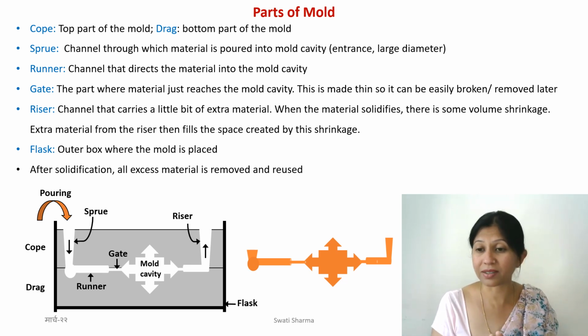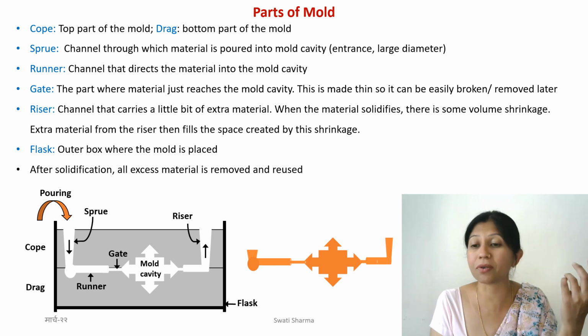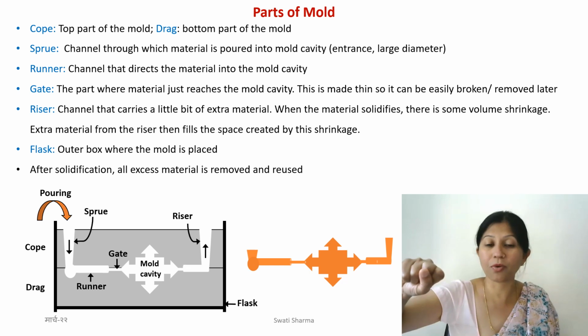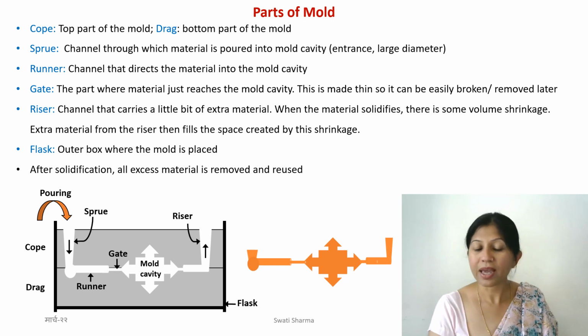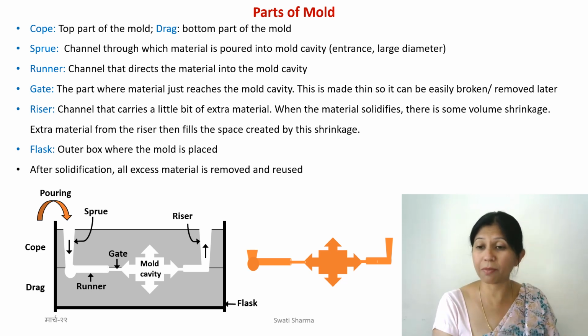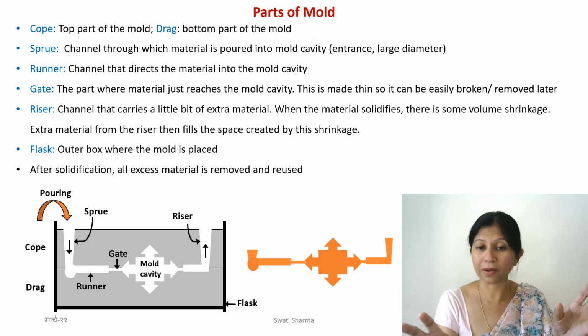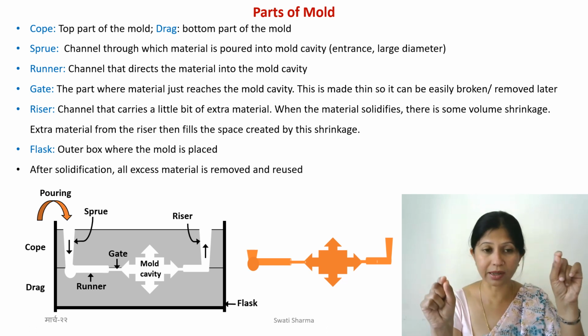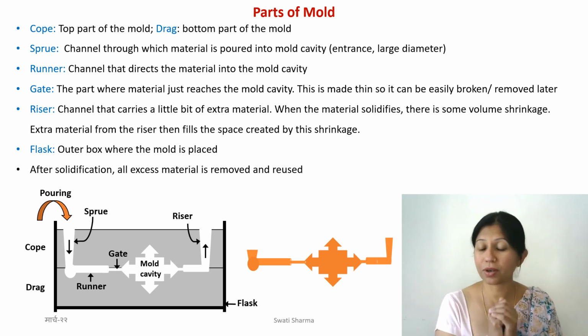Metal solidifies very fast, especially if you're performing the casting at room temperature. If you take aluminum, for example, it melts above 600 degrees, and you need to actually heat it a little bit more, so around 700. So you have superheated aluminum, and that superheated aluminum you pour inside the cast, and within seconds it's going to solidify. Because the room temperature is so much lower than the temperature of the metal, everything solidifies. So you will have also the extra metal in the riser, the sprue, everything. So this is what you're going to get, this orange color structure.